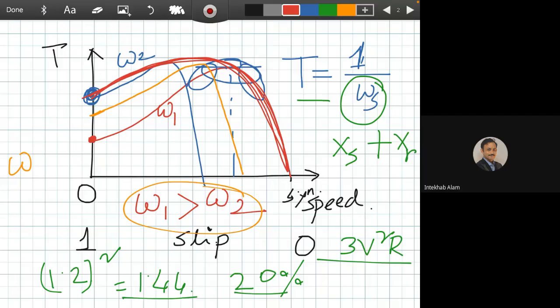But we can do it. If you want, we can do it. Obviously, the cost is different for each inverter and the quality of the lookup table of the motor, because the control circuit dictates the inverter to generate the frequency. How will it generate? It must start at a low frequency. If you make it very low, then the starting torque may be very high, so you'll find a jerk. So we can use a soft starter there.